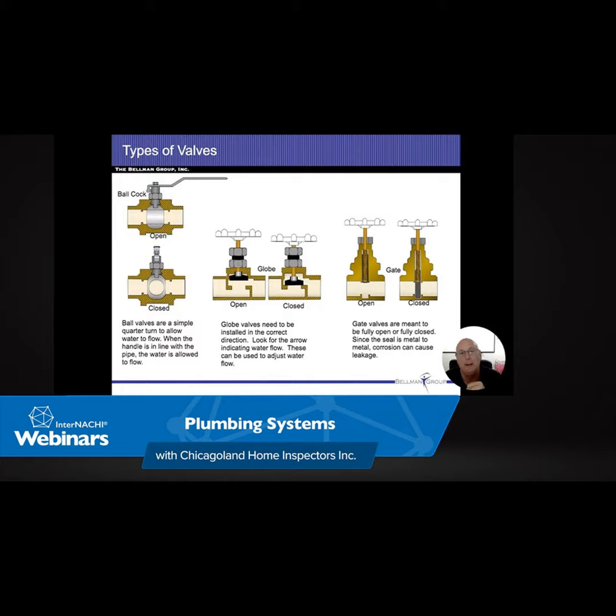When it's not working well, you're going to start getting sewer smells in the backyard. Any sewer smells outside is an indicator that something's going wrong. Now, we don't necessarily have to diagnose it. It doesn't fall under our field of work. But I think we would be doing our clients a disservice if we didn't tell them that they need to get somebody out here who's aware of this. Where we can keep stuff in tile beds too, we have to stay 50 feet away from lakes, rivers, things like that, 15 feet away from a house, keep it away from the lot lines, and keep the septic pit away from the house as well.